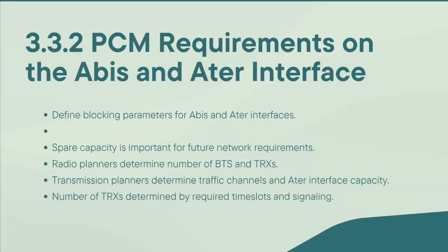So you might wonder what exactly are A-bis and Ater interfaces. They both are interfaces used in cellular networks, especially in GSM, which stands for Global System for Mobile Communication. A-bis is an interface between the base transceiver station and the base station controller.